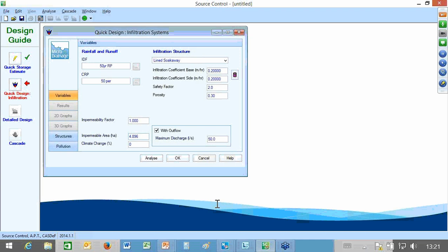I want to go right back up into the site and have a range of attenuation or infiltration structures scattered around the site, so we're holding back the flows, slowing down, and really just putting in a lag time and treating all of the rainfall back at source as best we can, and then on a site level, and certainly at a regional level when we're putting in the larger structures.